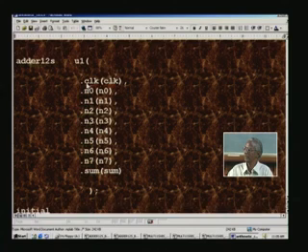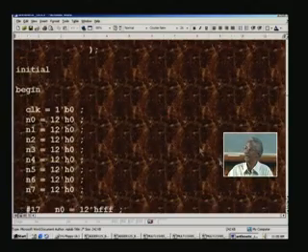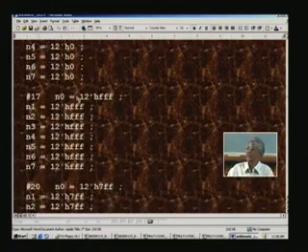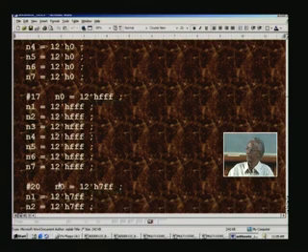For example, clock and N through N7 are inputs, and final sum is the output. And then we start the real testing process by initializing with a begin and matching end, and in between at different points of time we will keep on changing the various inputs. For example, all the inputs are initialized to 0 here, and at 17 nanosecond, so let us say we apply a different number. In this case, all f means all ones.